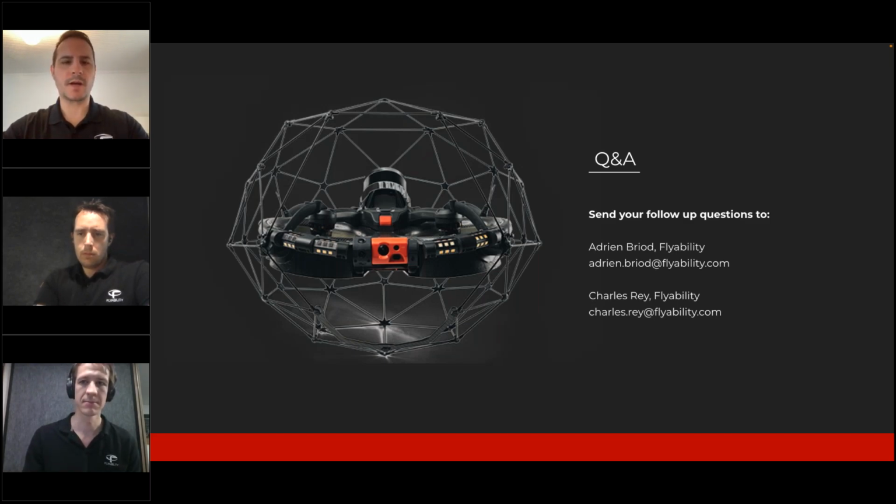Sylvain is asking, is it possible to use POIs as ground control points to register the point cloud with a previous topographic survey? It's a good idea. At the moment, no. I would say it would require that we have a feature where you can really position the drone very accurately in the same location over and over again for this to make sense, or to have some automatic extraction of some visual targets that are then fed. But at the moment, no, it's not part of the features. But point taken.